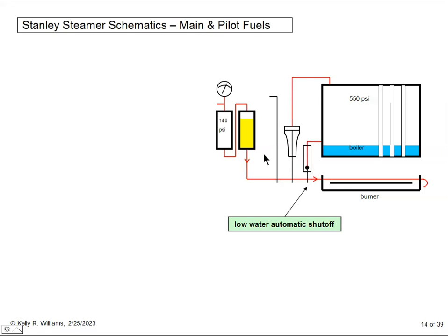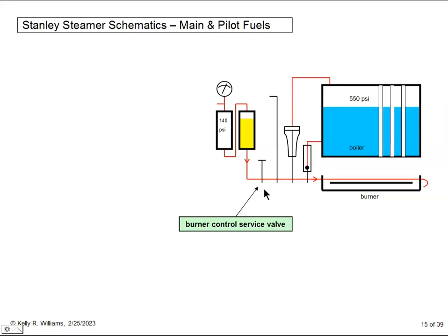If you look at the pressurized fuel here, you can see that it's always pushing against at least one of these valves. When the fire is out, we might need to service one or more of these valves, or we might need to do some diagnostic work. We'd like to be able to do this without all of the fuel in the pressure tank being pushed out. So we add another hand valve at this point in the line. This valve is within reach of the driver, so it could also be used to shut off the fire in an emergency if several of the other valves failed simultaneously. And that's it, the entire pressurized portion of the main fuel system and its controls.